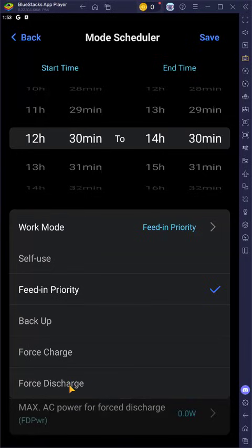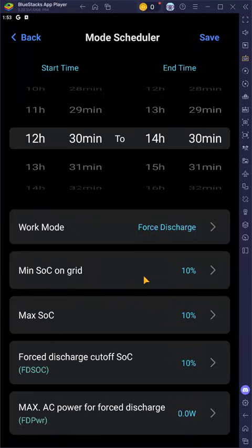The other one that a lot of people get confused about is forced discharge. This is telling the inverter that you want to use battery power and output it from the inverter. House loads are covered first, and anything not used by the house will then go to the grid and be exported. So where you see an opportunity to export during a peak time, is it 5 to 7 p.m. on Flux, you get a preferential export rate.